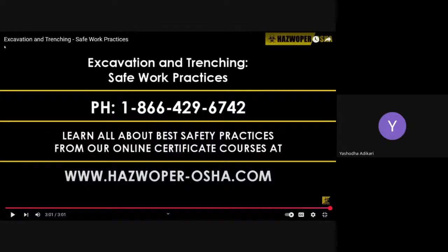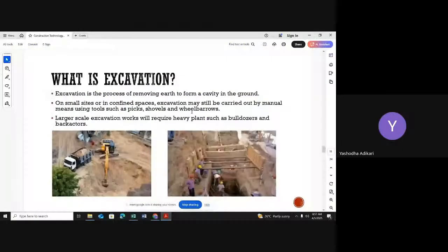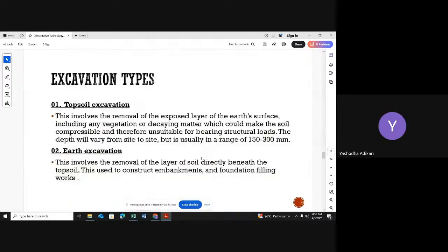Right, that's enough about the deep excavation, and at the same time the small scale excavations. So now I think you have an idea about this excavation, especially for the large scale excavation. In this picture it's showing a shoring. We can use different types of shorings with different types of material. It's up to the requirement, but the purpose is labor safety and protection of the excavated surfaces. All right.